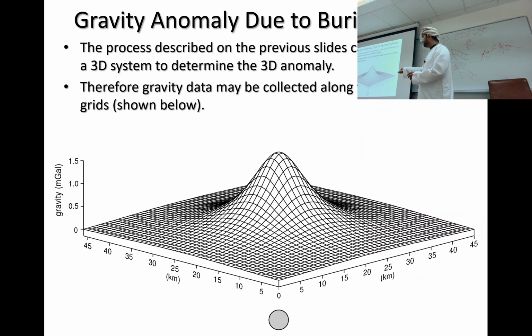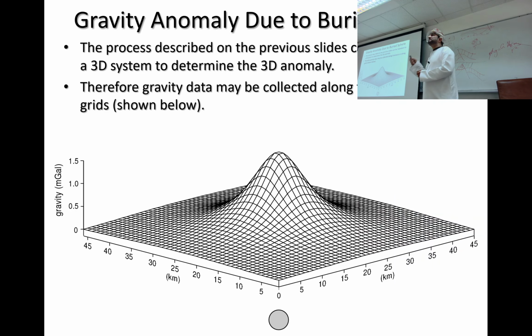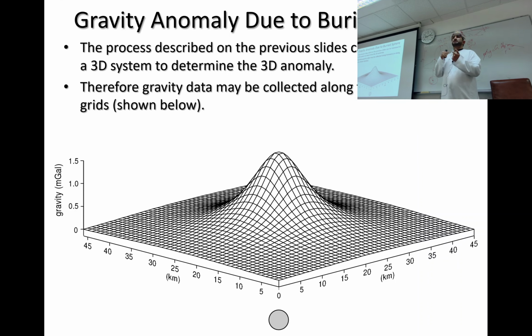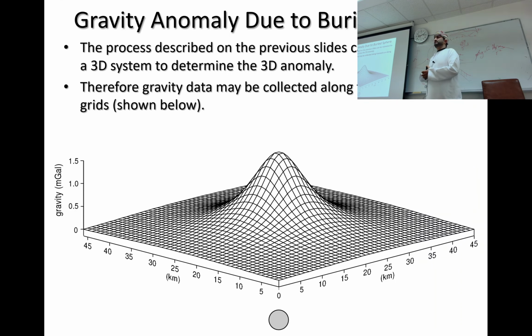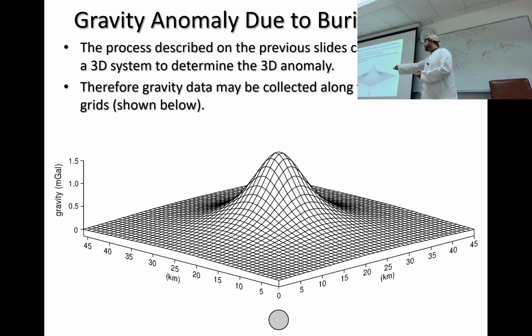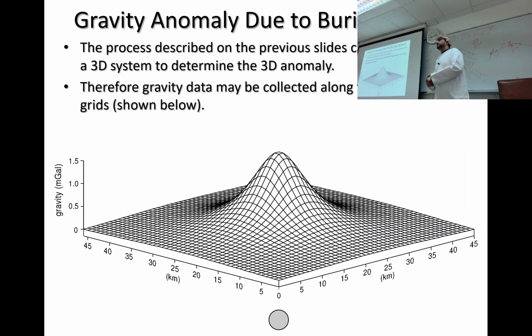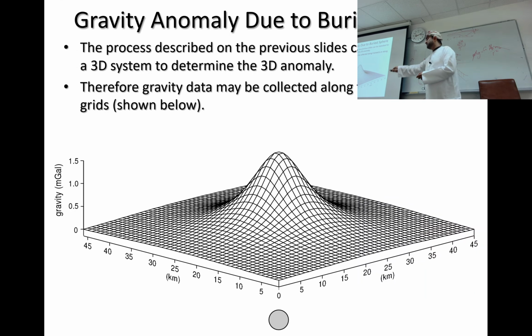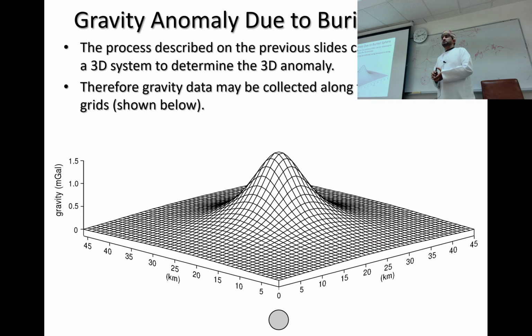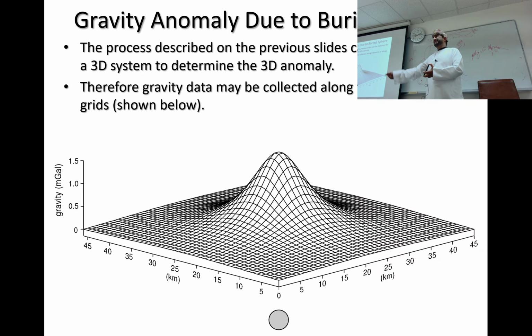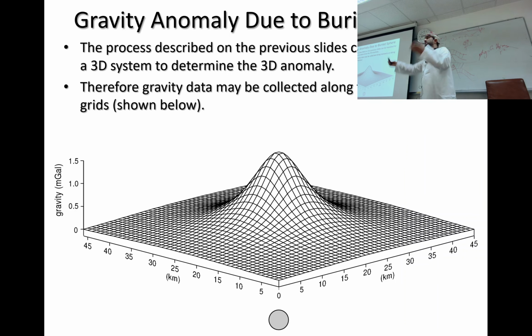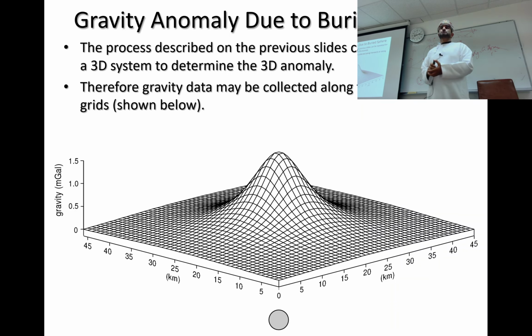The value you get here is in milligal. It's the difference in gravity between one point and another point. It's not the absolute value. It's not 9 point something. If it was 9 point something, it would have been a large number in terms of milligal or gravity units. And 9.8 meters per second squared, if you convert it to milligal, is going to be a very large number.